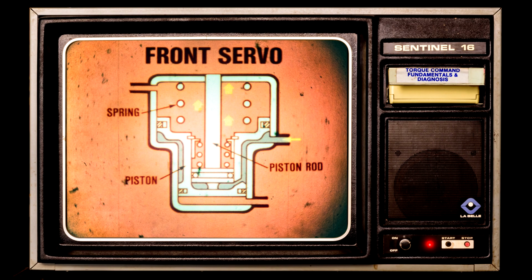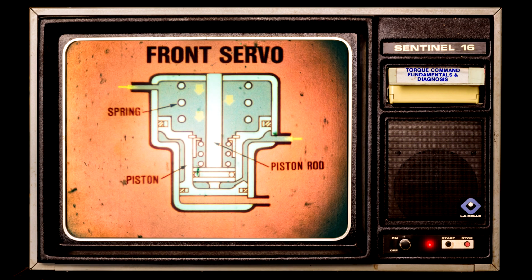Continuing with our different hydraulic pressures, apply pressure applies the front band in drive range second gear and manual second gear. Basically, this is how the front servo works. Line pressure is applied between two lands of the piston. The pressure on the larger land forces the piston up so that the piston rod forces the lever to apply the front band. Servo release is accomplished during the 2-3 upshift by line pressure combined with spring force acting on the reverse side of the larger piston land. This releases the front band.